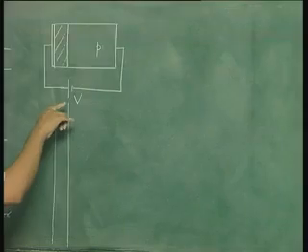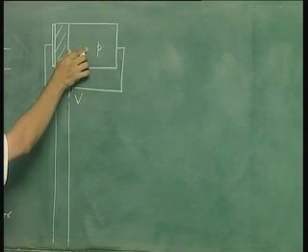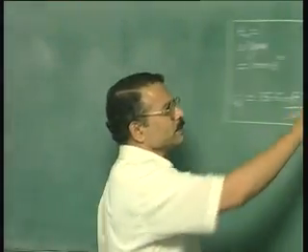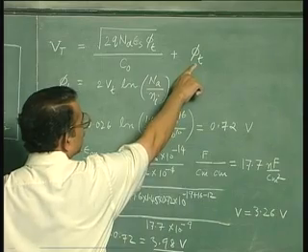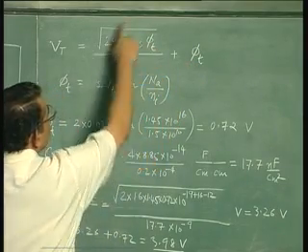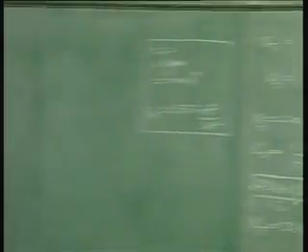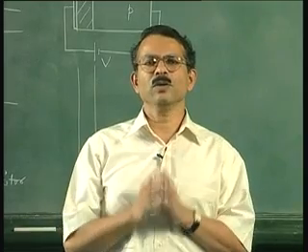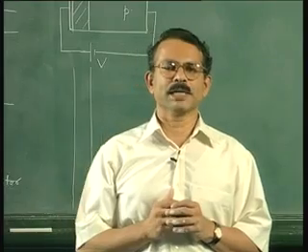Out of this approximate value of 4 volts, please note that only about 0.7 is falling in the semiconductor, that is this value here, phi t, which is psi s, the potential drop in the semiconductor, and this is the potential drop in the oxide. So you find that most of the applied voltage falls across the oxide and a very small value falls across the semiconductor. This is something important that we must gather from here.